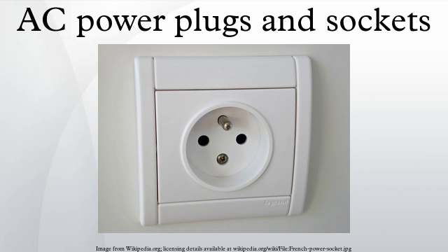Add to that, the French convention changed circa 2002 from nothing particular to: if the earth pin is at the top, then the line hole in the socket would be on the right looking at the socket. However, the socket may not necessarily be installed with the earth pin at the top. Packaging in France of said sockets is normally marked with the correct orientation of the cables.